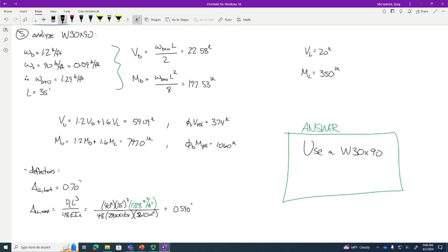And if you want, you can say the performance ratio for moments, if you chug it out, is like 0.752. The performance ratio for shear is 0.158. Again, W shapes tend to just have a phenomenal amount of shear capacity in beam scenarios. And then the performance ratio for deflections is 0.843. Now, note that this is the highest one.